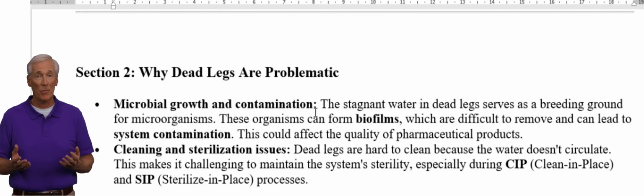Microbial growth and contamination. The stagnant water in dead legs serves as a breeding ground for microorganisms. These organisms can form biofilms, which are difficult to remove and can lead to system contamination. This could affect the quality of pharmaceutical products.